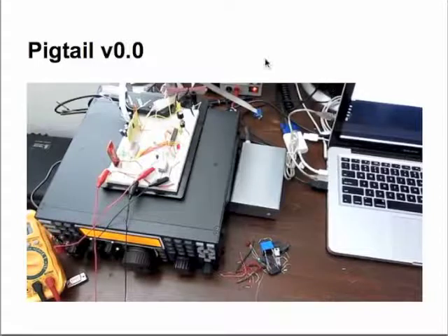So this was me on the bench just seeing what I could do. This was actually Bluetooth for Android, and this is from SparkFun. It's a little breakout board for a Bluetooth serial module. We had a level shifter here plugged into the K3. The Bluetooth module was going into this PIC. This is a PIC microcontroller, and this little box right here is actually a mechanical relay. So it was doing on and off keying at variable speeds. So it had a keyer built in.